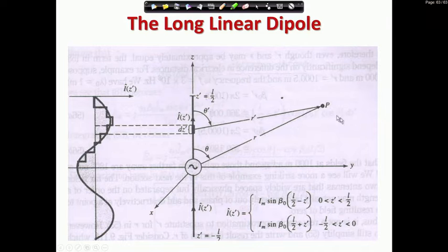One thing is that we will have the spherical coordinate system, with the center of the source as the origin. P is a point characterized by r, theta, phi. So, P will have a radius vector r, then theta its angle, and then its azimuth will be phi. Similarly, a current element at a distance z, with a coordinate dz dash, will have a radius vector r dashed, the angle is theta dashed, and the z coordinate is z dashed.